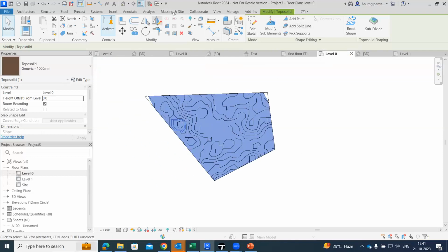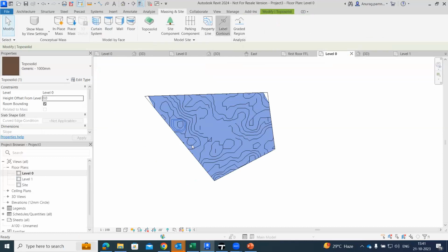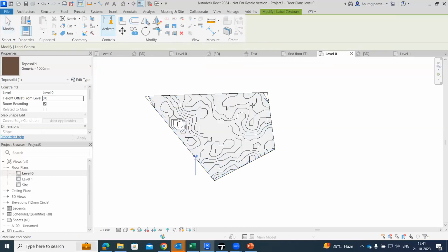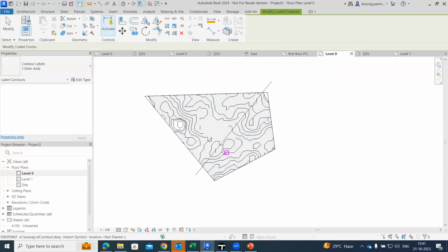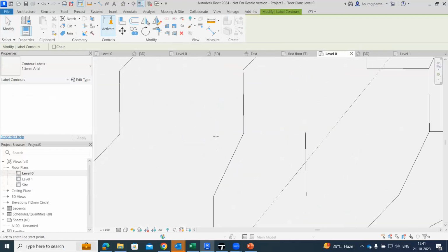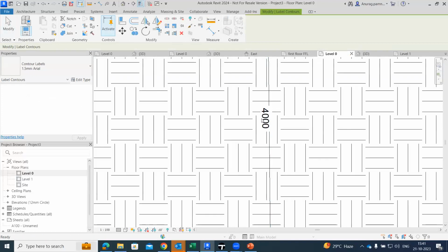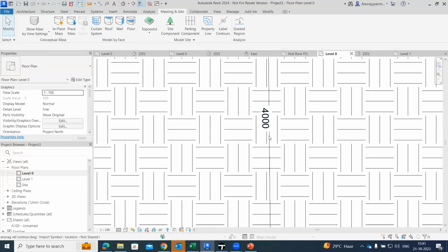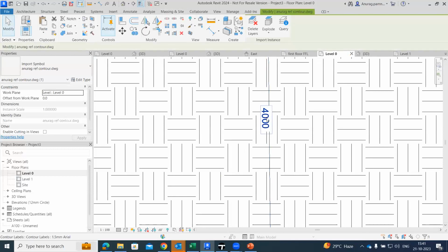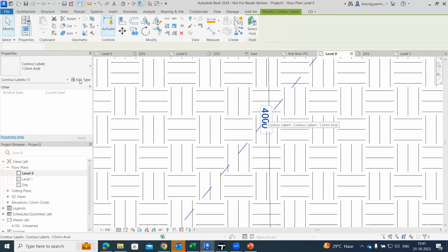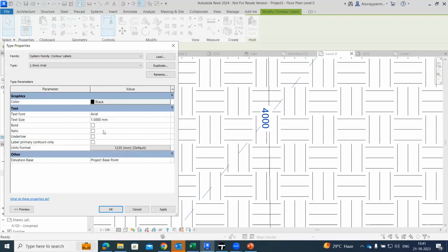And we will be going back onto Massing and Site, say Levels. We can just click on this, and over the particular line, we would have got the levels over here. As you can see, it already appeared, which has taken the CAD data itself directly. I can edit this and make this type style of level as, say, 100 mm.